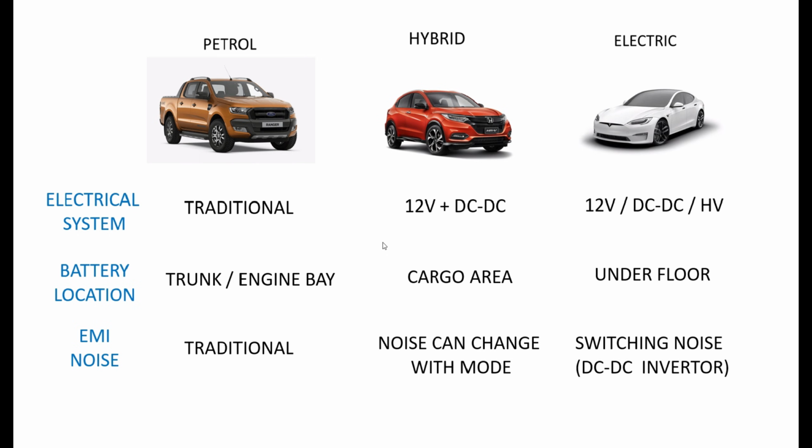Now, in terms of EMI, the noise can change depending on which mode you are operating your car in. So, I don't get noise when I'm running it in petrol mode, but as soon as it switches to electric, I may get some switching noise from the DC to DC inverter that's operating in the hybrid, right? So, you just need to be aware of these problems and factor this stuff into your car audio design, particularly if you're using, for example, a hybrid or EV.